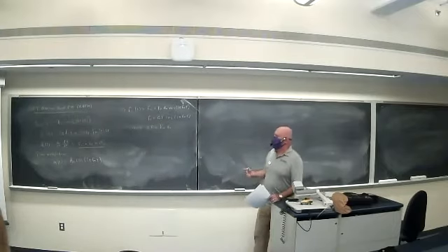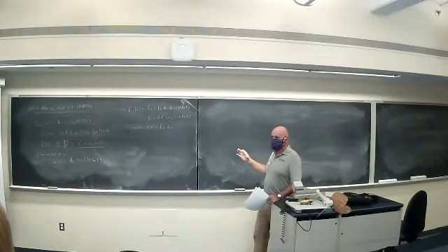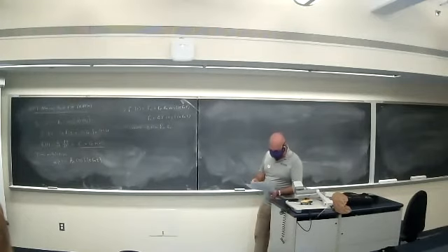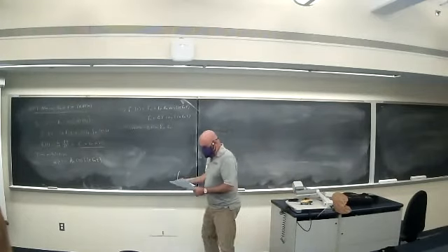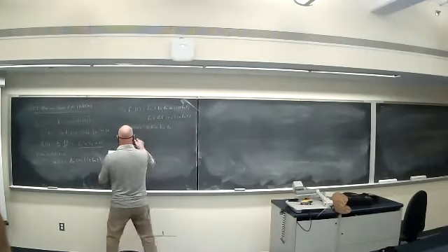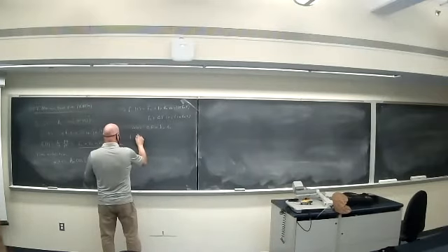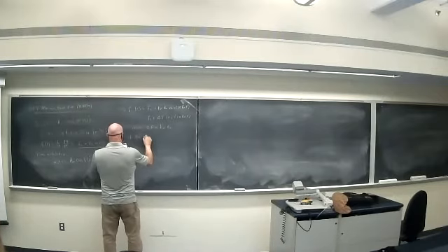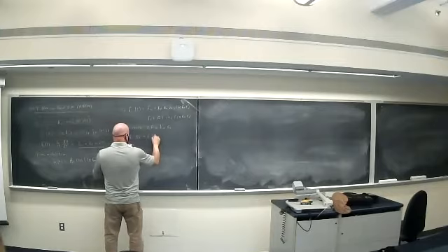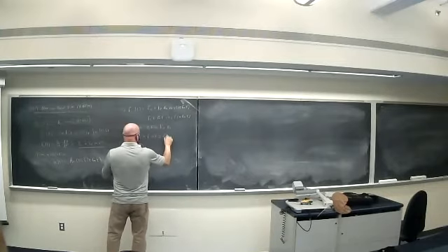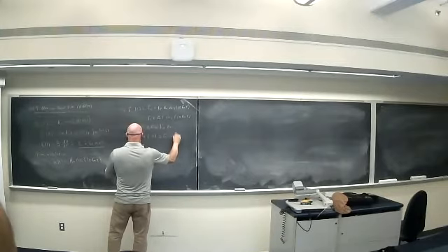And again, the instantaneous frequency goes delta F above, delta F below. It appears that this thing might have a bandwidth of 2 delta F. Okay, so FC minus delta F is less than the instantaneous frequency, which is less than FC plus delta F.